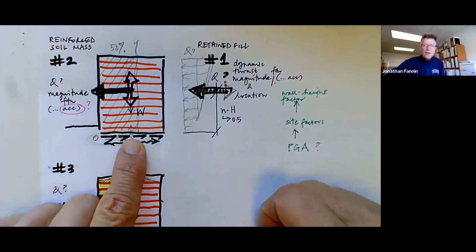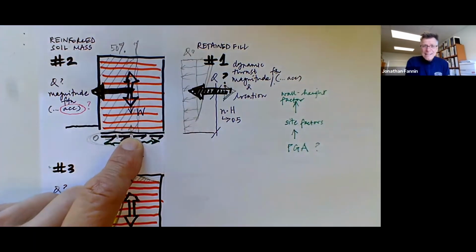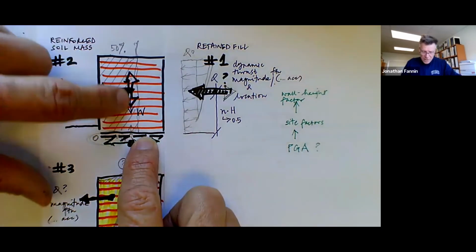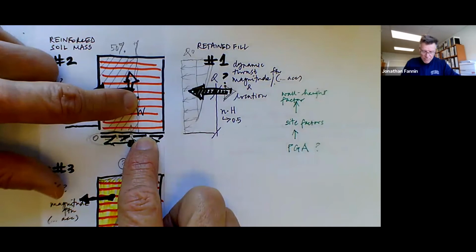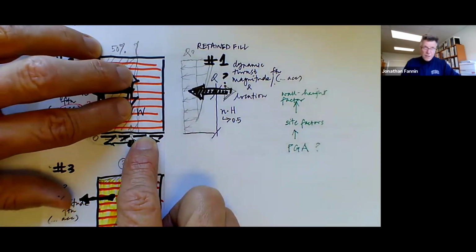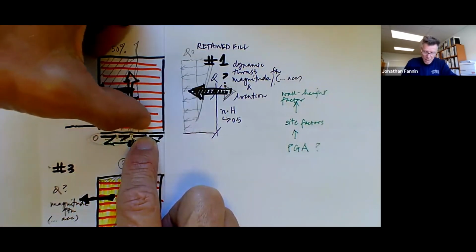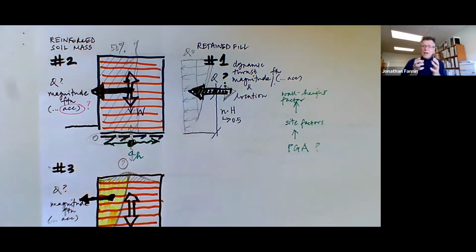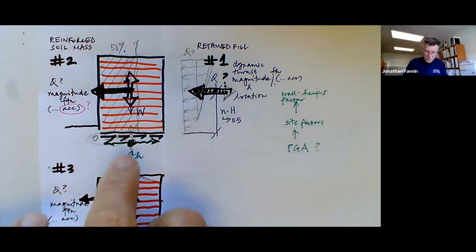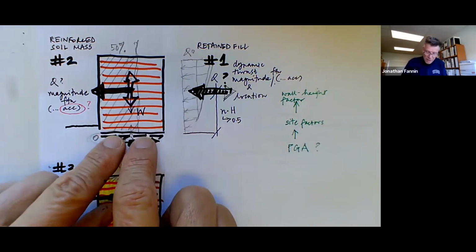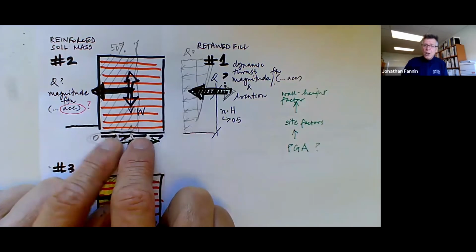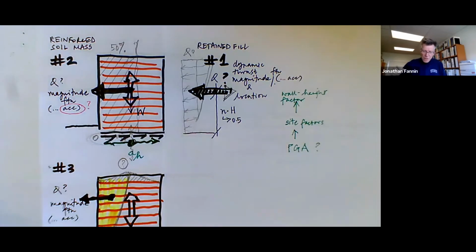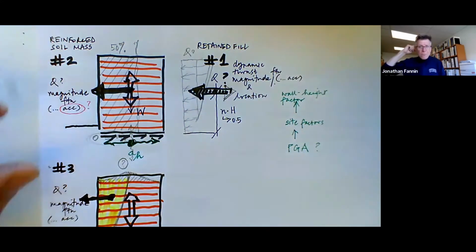And then on the capacity side, if you're looking at sliding resistance, as Sarah observed, yes, there'll be vertical and horizontal acceleration, vertical acceleration up and down. And thus the nature of the effective stress will change here, or might you capture that by diminishing the interface friction and allowing yourself only to mobilize a lower proportion of the interface friction here. So that's the system response.